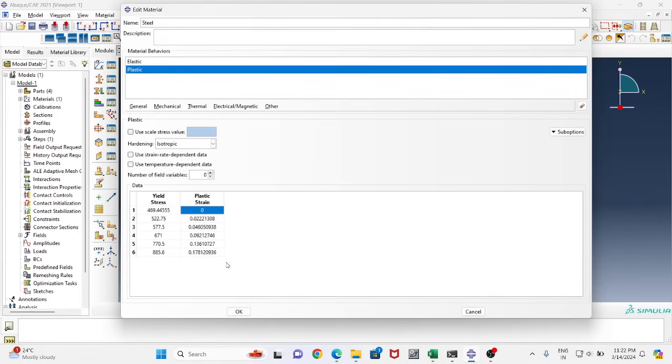Now this is how we define the reinforcement. And here we didn't consider the change in material of reinforcement depending on the diameter. Since we have two diameters, if you have the data for 8 mm and 10 mm, then you have to define two different materials, one for 10 mm diameter and the second for 8 mm diameter. But here we will consider the same for both diameters.